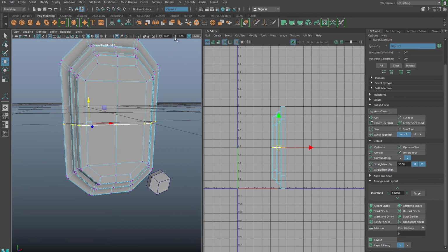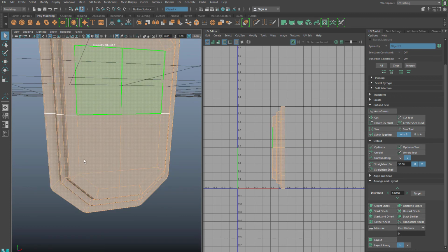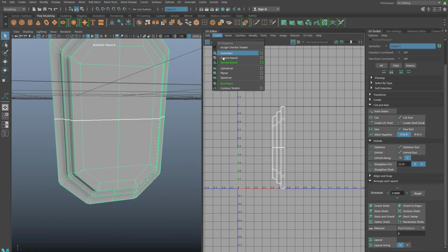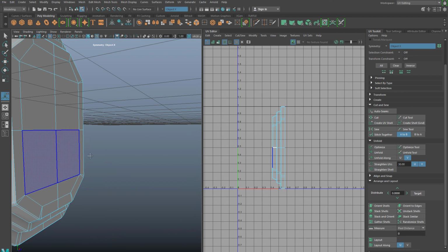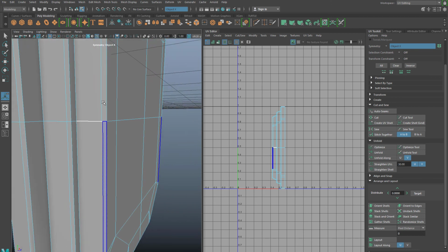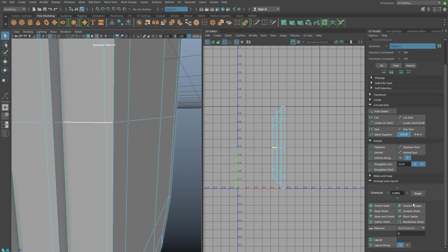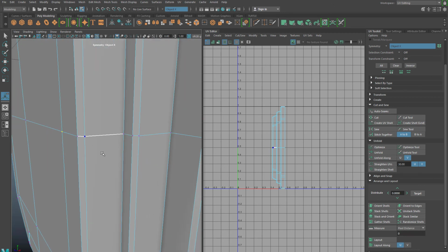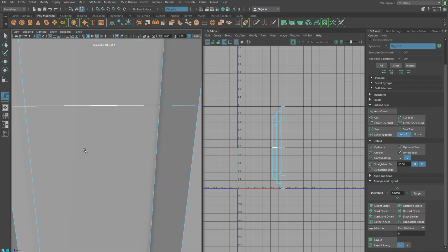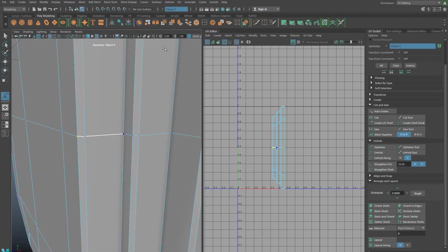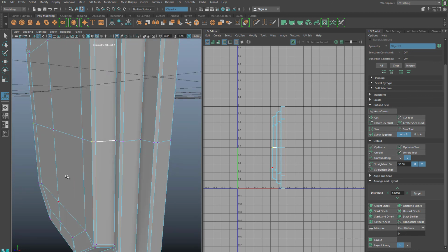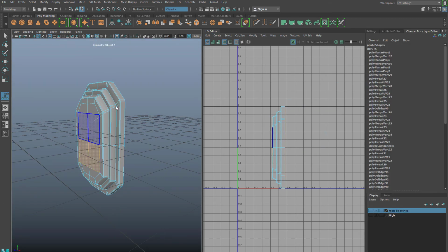So let's just take this and we'll merge those vertices because that needs to all be one wonderful piece, and then we'll go back and create a planar map. Now that means you're not welded. Oh, okay. Look at that little disconnection going on here. So let's go to vertex, take those two, weld it. All right, now it's all one wonderful piece.